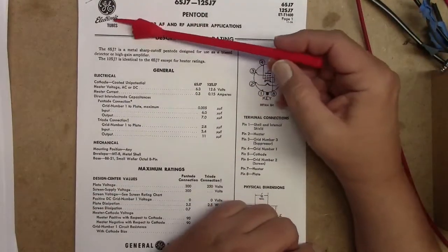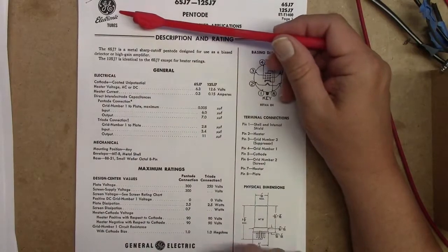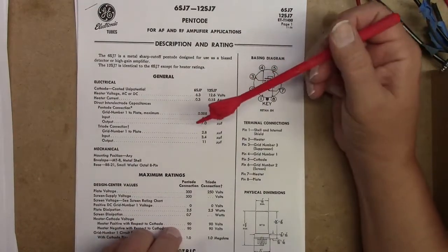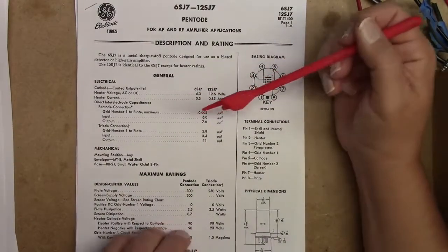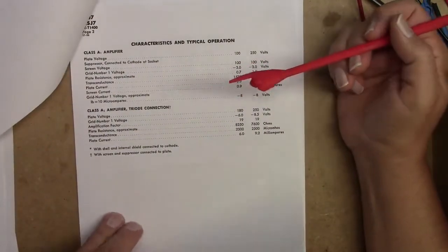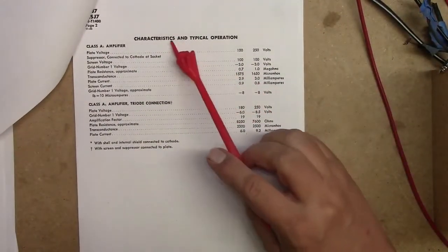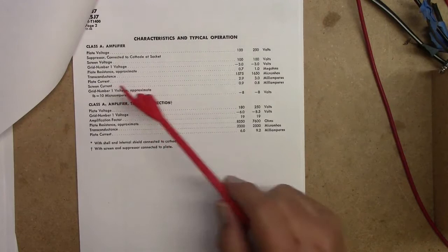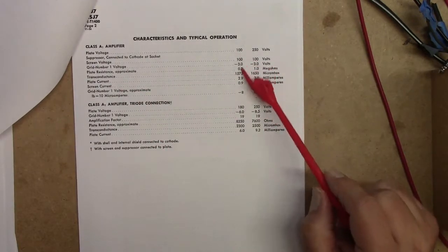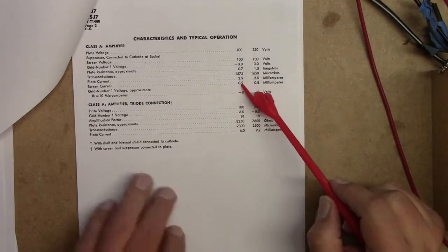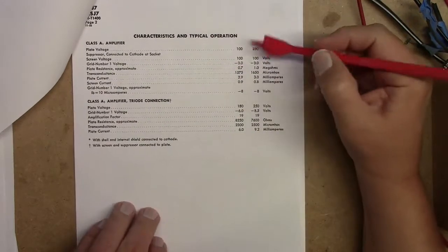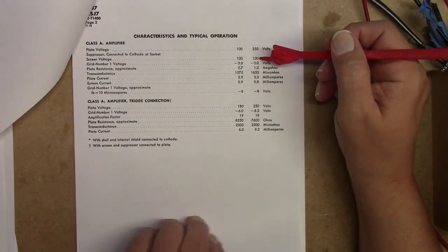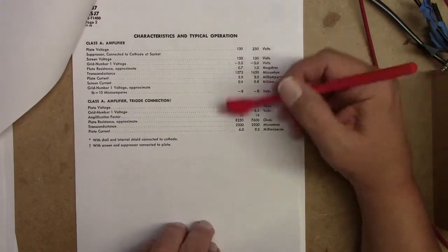I found in my studies here that GE data sheets are a little bit cleaner because they're a little bit newer, and there's just a lot more information in a GE data sheet. So we'll just go through here. We're not going to look at any of this stuff because typically, these characteristics here are written by the General Electric or the RCA engineers, and they're giving you the values here that'll give you the optimal performance in terms of distortion. But you can see from here, if we're running the plate voltage at 250 volts, they suggest you run the screen voltage at 100, but we're running actually at 16, so none of this actually applies.